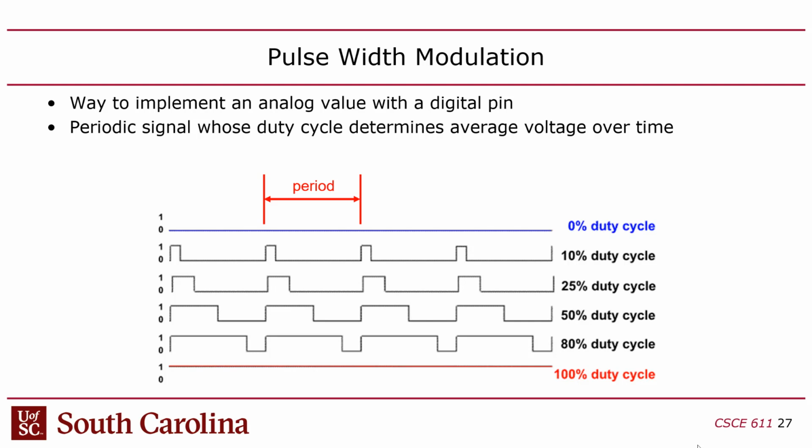Now the PWM signal, some of you have seen LEDs that dim, that pulse, that get brighter and dimmer, like those ones you hang up on your wall, right? Those use PWM. So what that implies is that the PWM duty cycle is dynamic. It can change. If you have a pulsing light, it gets brighter and then dimmer, brighter and then dimmer. So that duty cycle is changing over time. But if you looked at the individual periods, it would take a long time to change.